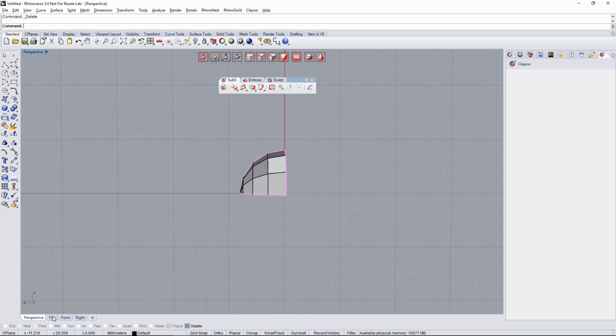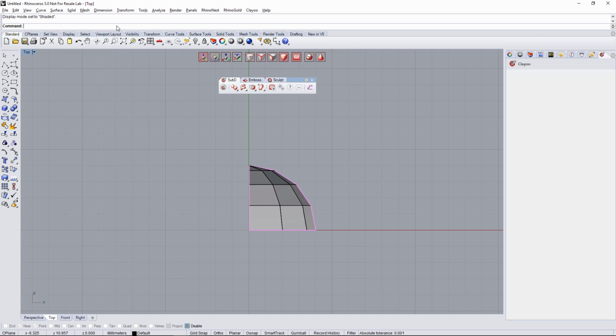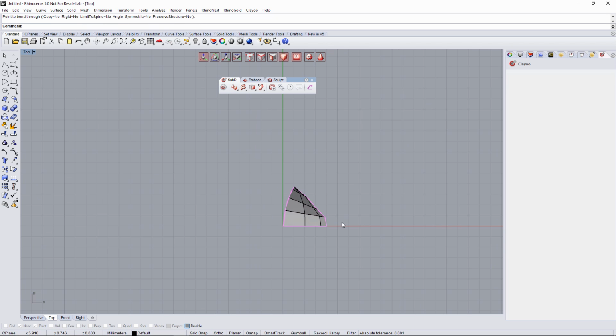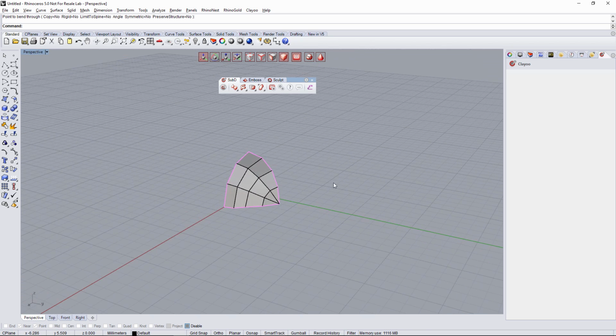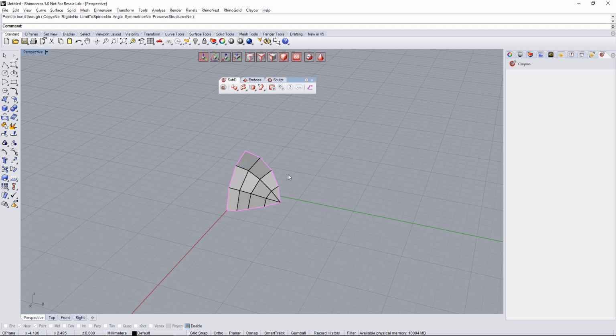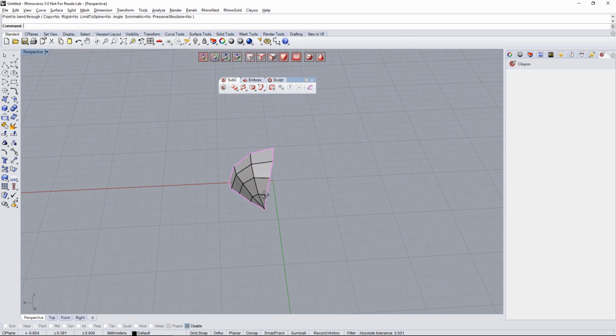Okay, so what I'm gonna do right now from the top view is I'm gonna bend this object. So I'm gonna select the entire object and I'm gonna use the command bend, the Rhino one. So I'm gonna set that from here to here, it's gonna be the spline to bend, and I'm gonna bend a little bit. Okay, I think something like that's gonna be more than enough. So from here it's gonna start the shell. Perfect. Right now I'm only creating one half of the shell, so then I can create the symmetrical object. So I don't care about the other half of the model.